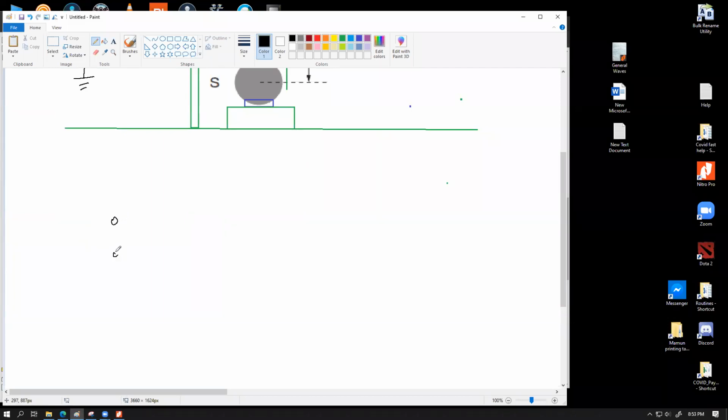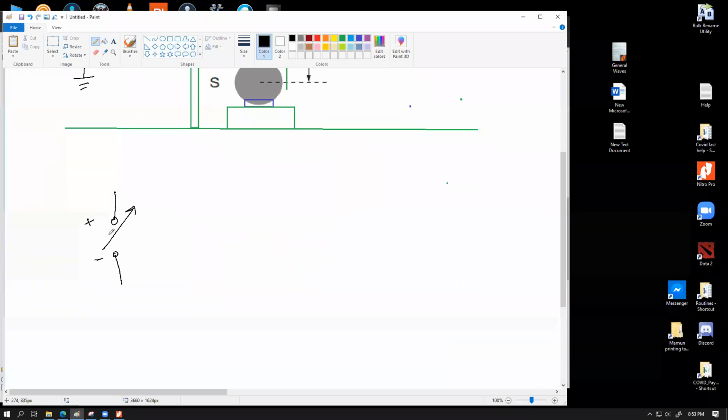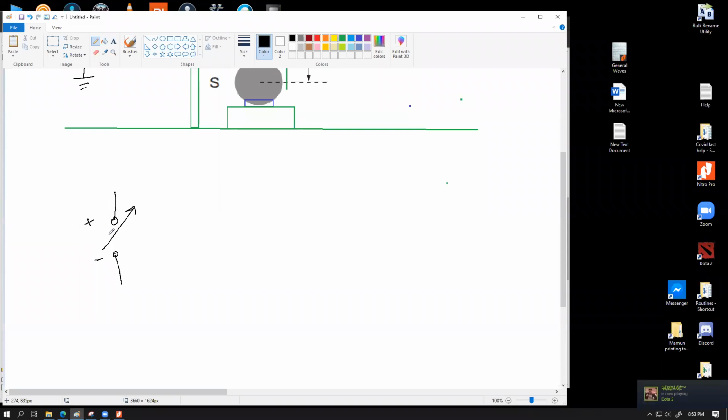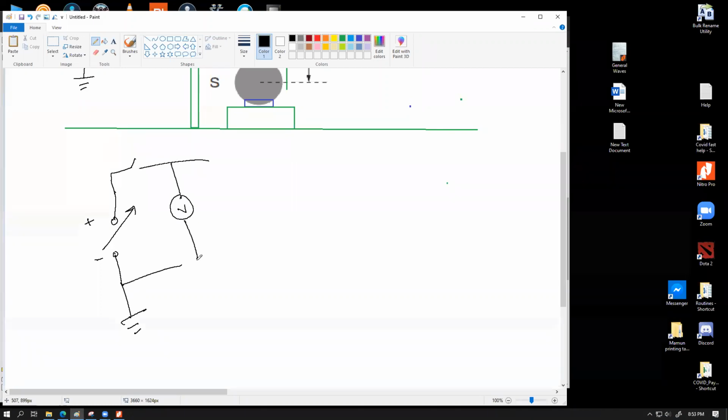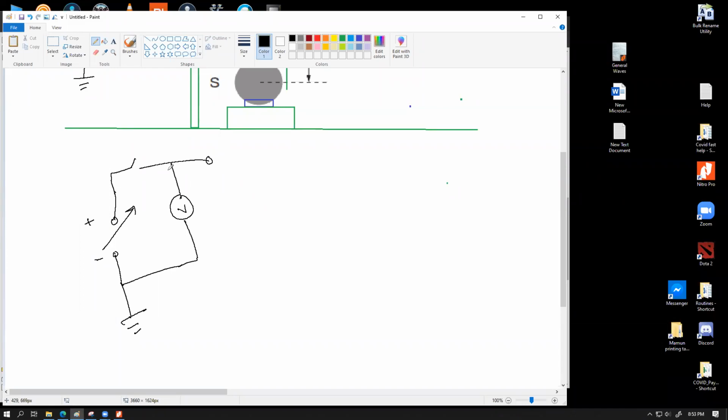For example, let's say you draw a supply, plus and minus. You give an arrow in between. This thing makes it a variable DC supply. This arrow over here means this supply voltage can be changed, which is basically how we can work with the rectangular power supply boxes that I have in my laboratory. Many of you have worked with them, or in other laboratories as well. So we can simply have a switch. We should always have a switch. And we can simply connect one end to the ground. And we can simply connect a voltmeter with this thing. This supply would just work as fine.